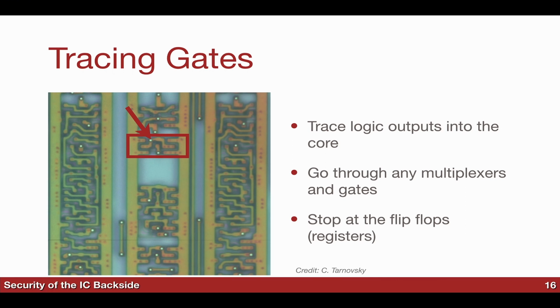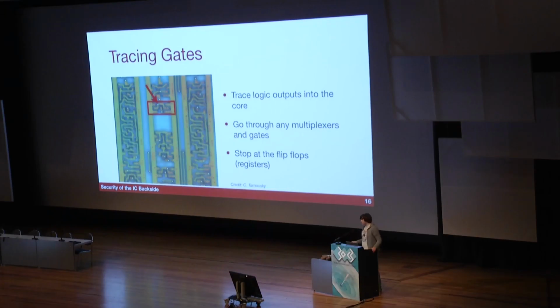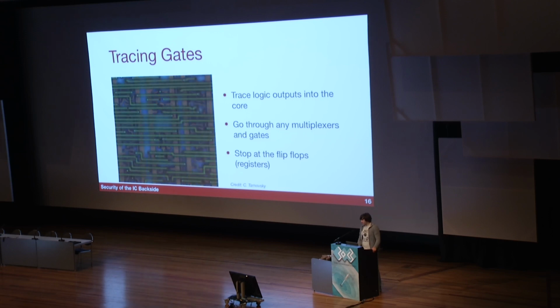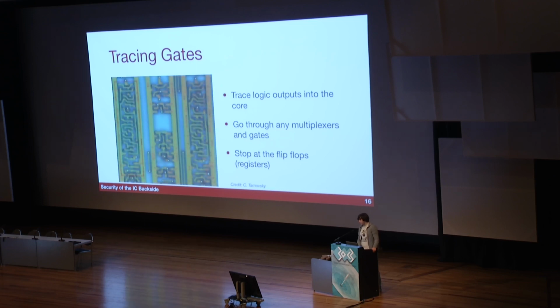You can actually see what's going up. It's the dot. So that's either the inputs or the outputs. That's the actual connection to the other metal layers. So now it's going up, obviously, because it can't go down anymore. This is the bottom metal layer. So now it goes up over here. And now we can see it goes over to the left and up, and boom, we hit the flip-flop. So that was the image we had before.